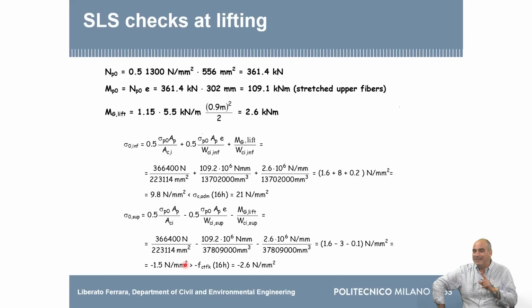But you cannot guarantee that there is really no crack, because you might have some shrinkage cracks, or the stress state might sum up with some temperature deformations and so on. So you might form some local isolated cracks. But this check guarantees that you will not have very high tensile stresses.